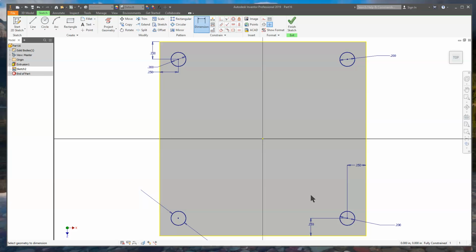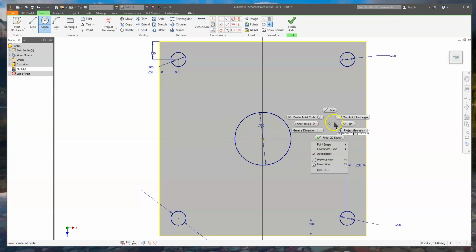Okay, I'm not finished yet. I'm still in the dimensions. So I'm going to right click, tell it okay, I'm done with dimensions. I could actually just click on this other command and come out of it also. This center hole, do you remember what size that one was supposed to be? Set 750 thousandths, that's correct. I put that hole in there and I put that on the center of the crosshairs. I put my square on that center, my hole is on that center. Now I know that this is centered up to that box, right?